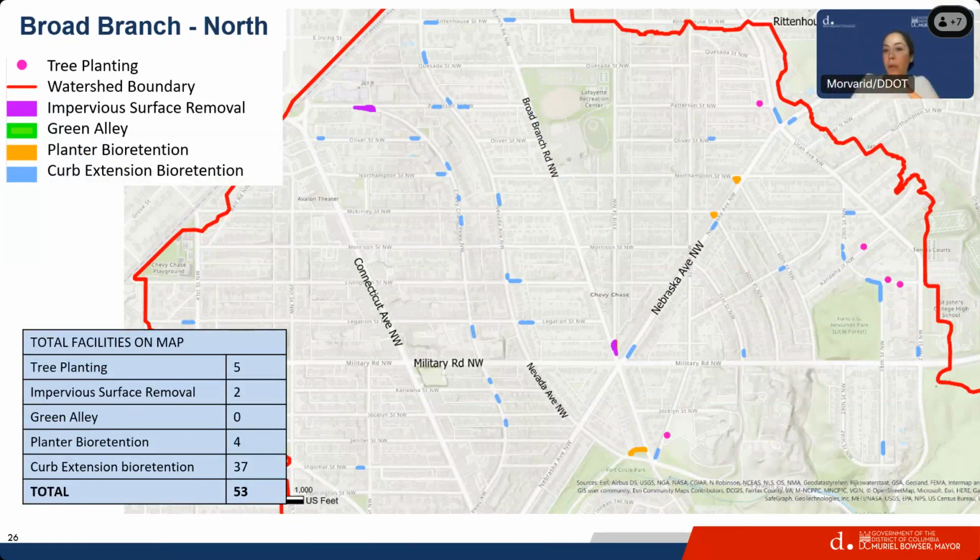There was no problem, there was storm sewer nearby. There was probably no existing tree to impact. It's relatively flat, or we have a catch basin or sewer, or we don't have any underground utility to conflict with. So these are generally the factors. I think this question was generally, why are there so many along Chevy Chase? Probably Chevy Chase is flatter than others. There's not much utility in conflict with the retention. The soil has been good. The soil has to have a good infiltration rate. There are no trees to be impacted. These are the general reasons that may limit us in site selection.